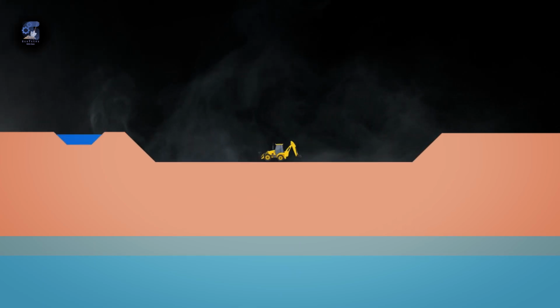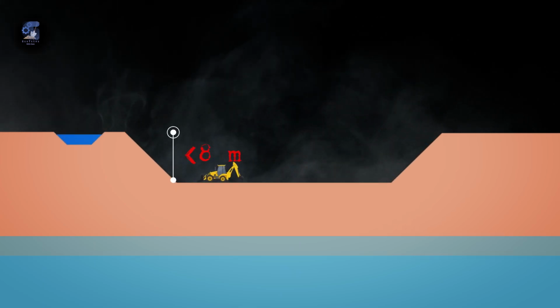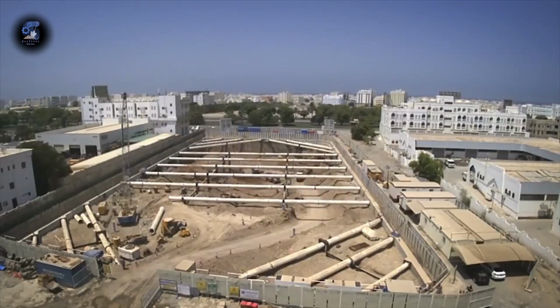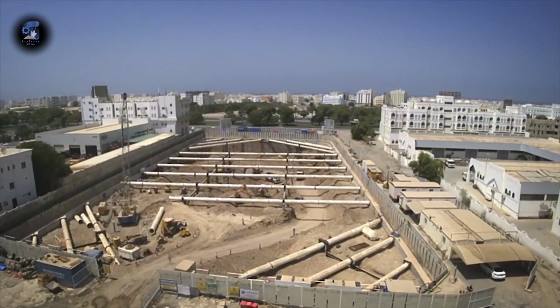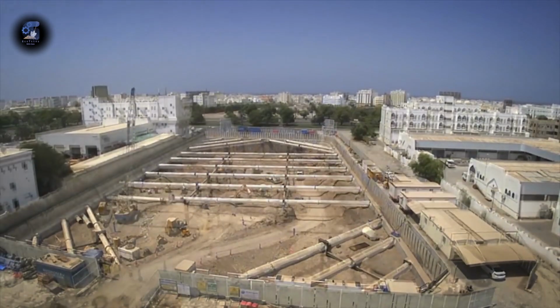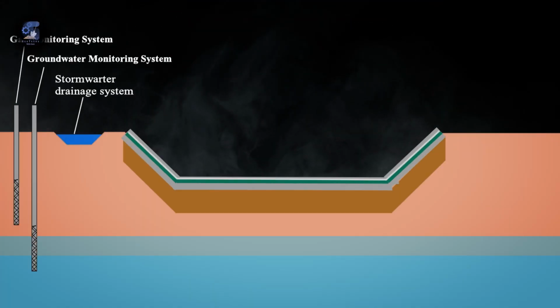When excavating the landfill pit, the sites are on a slope, and the depth is usually below 8 meters. This increases the local stability and does not require support such as deep excavation projects like those for underground tunnels and tall buildings. Once the excavation has been completed, a liner system is installed.